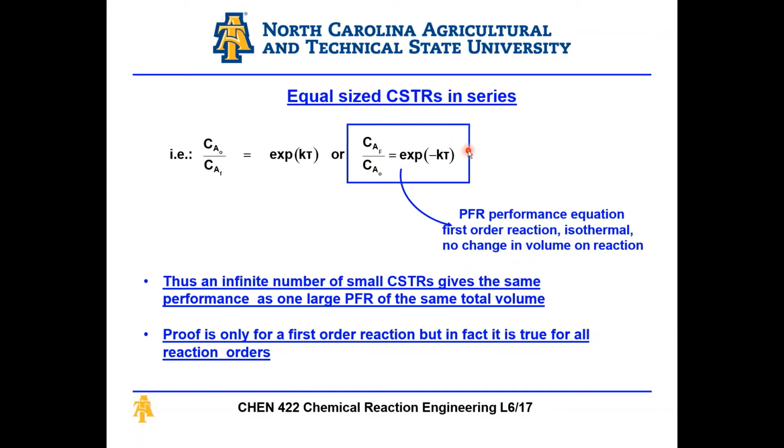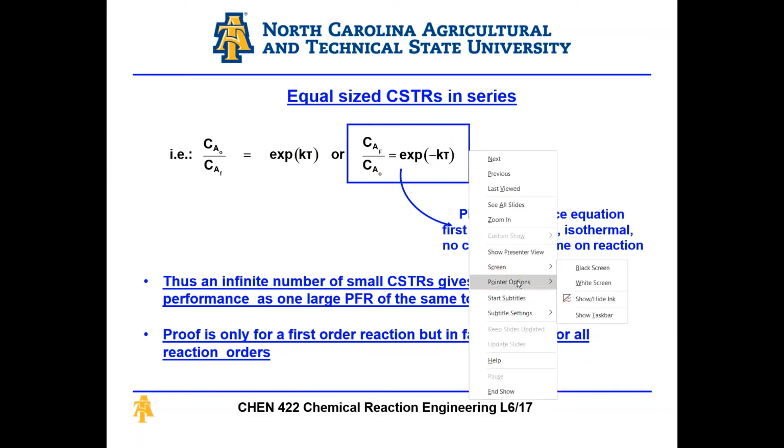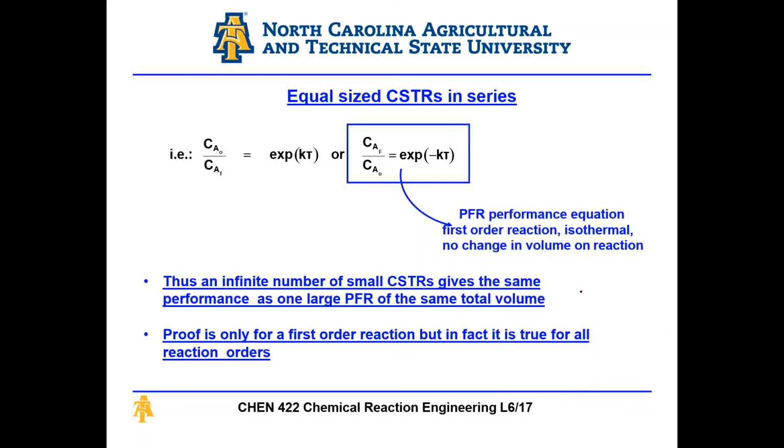Just one thing we need to be aware of is that this was derived under the assumption that n approaches infinity, right? So even though we made the assumption, we should not forget it, because we took the expression to a series format, removed the n's by assuming it goes to infinity, and then reversed it to another type of series format. So just be aware. And this is the performance equation for equal sized CSTRs in series.